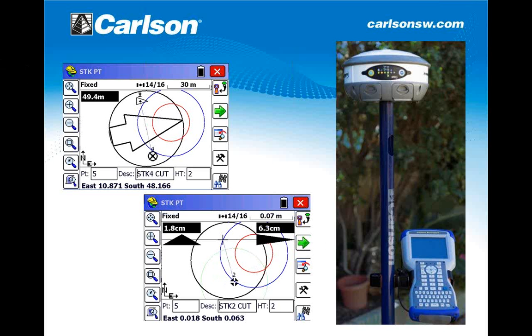So one could be auto store when level. You all know in SurvCE we have auto by interval, which can be time or distance, and this will be a third option for leveling condition, right? Again, we have a leveling tolerance, so when this condition happens, you don't even need to press the enter key. For a quick survey, it would be a really productive feature, okay?